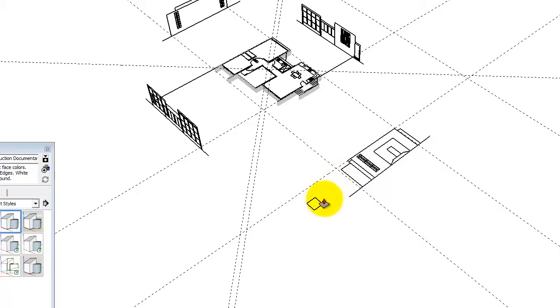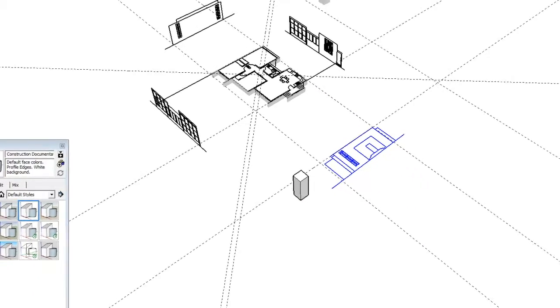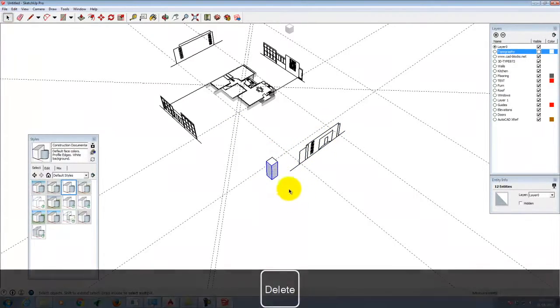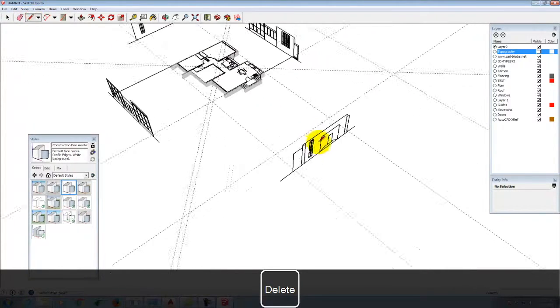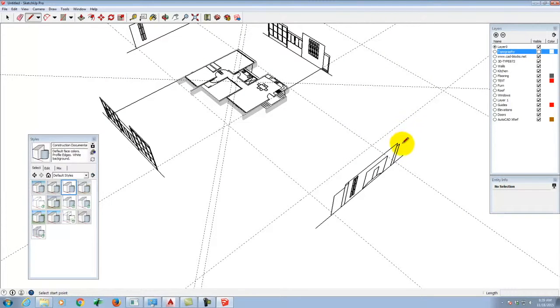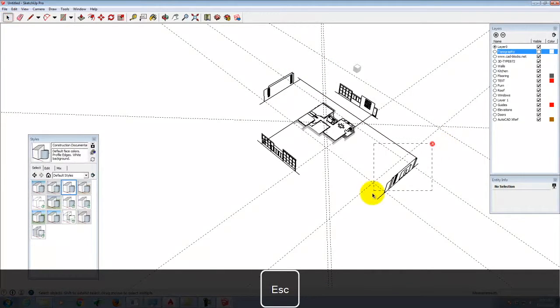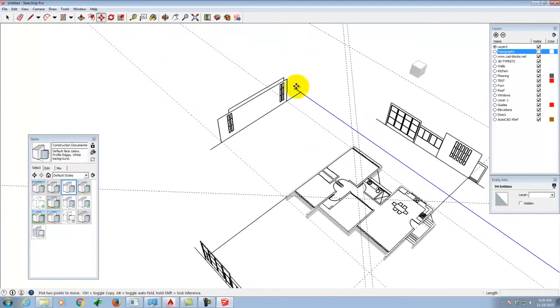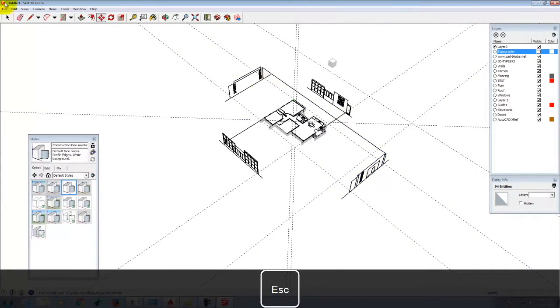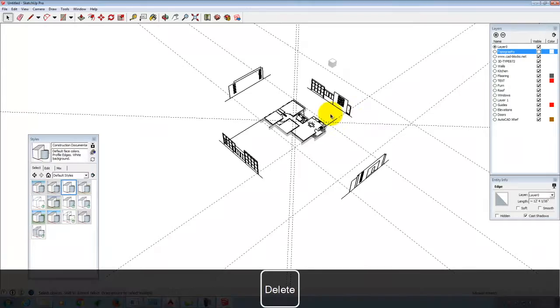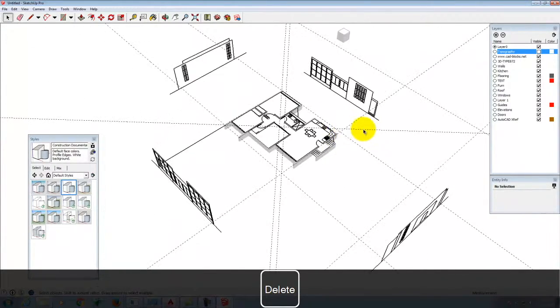There we go. Pull this up. And we'll rotate again. And there. I can make sure that these line up by going way over here and moving all of this right there. And so this works easy and clean because I've already spent the time to orient these elevations in my AutoCAD drawing. If your AutoCAD drawing doesn't have all the points, it'll be a little bit more challenging to line this stuff up, but it's up to you in terms of how you do it.